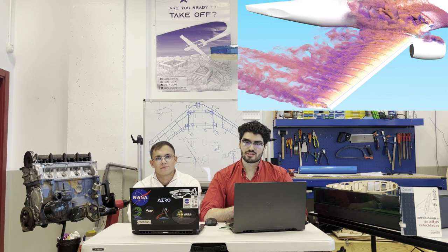Thank you, Sergio. A better model would include a CFD analysis, namely an LES or DES, large eddy simulation or detached eddy simulation, solver with a k-omega turbulence model. This would therefore capture all the effects that have been neglected. For example, wave drag, turbulence, and other effects like trim drag and stall.